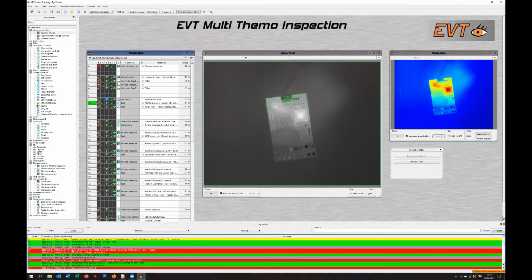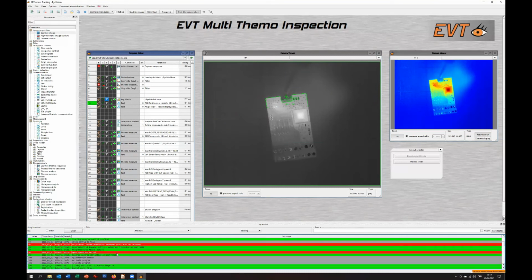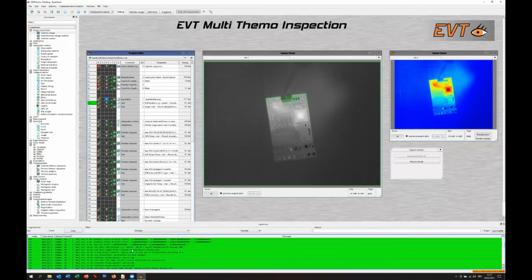Or, for example, sometimes I have an RS-232 interface to the PC by USB, and of course right now I don't have it here. So if I wonder why I cannot send out data over RS-232, it's because it's not connected. So it's really helpful to have a look at it.